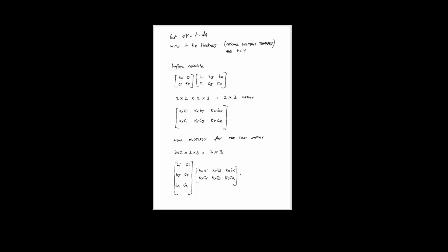We have to perform some matrix calculations and some simplifications. For example, in a two-dimensional problem, we can write the differential dV equal to t multiplied by dA, with t the thickness of the plate. If we assume uniform thickness inside the element, we can also simplify further by putting t equal to 1.